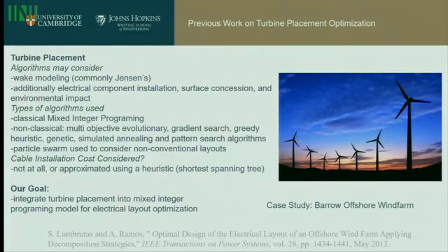So just as an overview, oftentimes when people are trying to figure out turbine layouts for wind farms, there are a number of factors that they consider. The biggest factor is obviously the wake interactions between the different turbines, because if turbines are closer to each other, you have a wake effect from the first turbine slowing down the air velocity by the time it reaches the second turbine, decreasing power output.